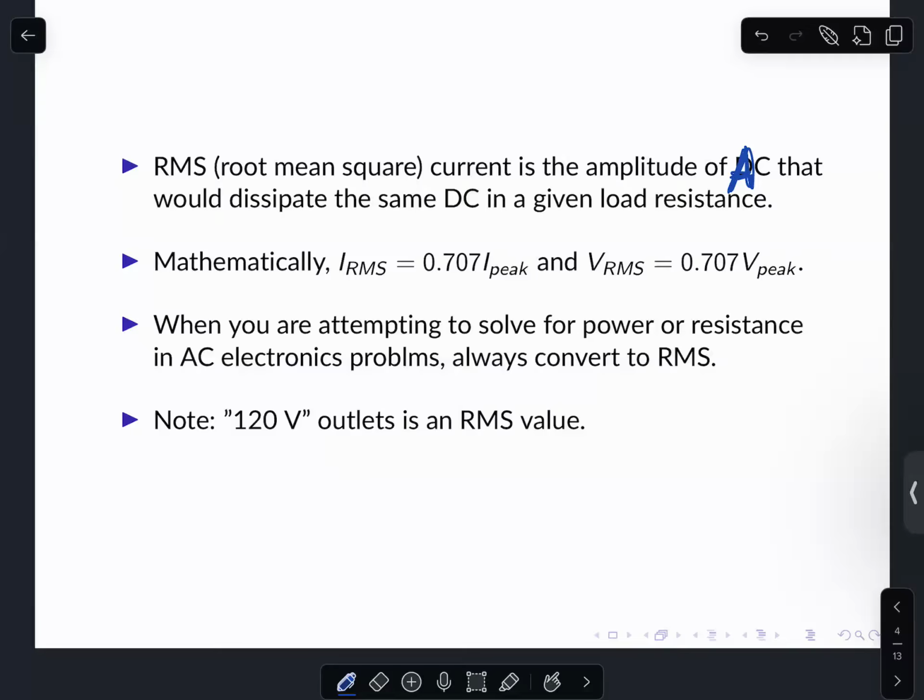Let me say that again, but backwards. If you had a 120 volt battery, you plug your toaster into that 120 volt battery, it would dissipate whatever wattage the resistance of that toaster would give. When we talk about 120 volt alternating current, we're talking about the RMS, the averaged voltage, the root mean square voltage. The peak value, if you were looking at a graph, what you would naively think is the amplitude of the sine wave, that's actually 178, if I recall correctly, 178 volts.